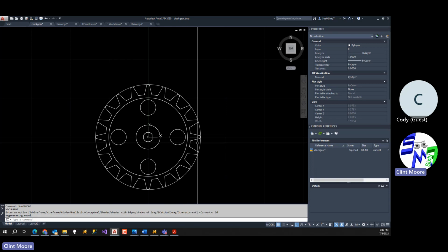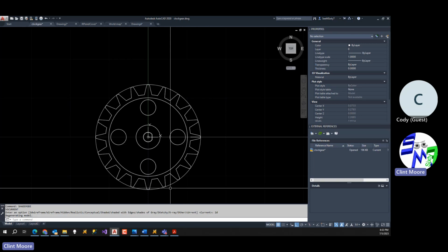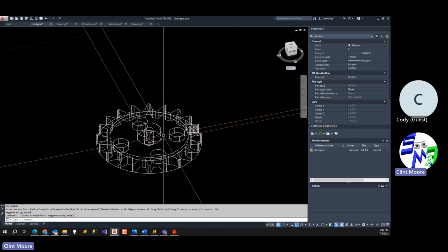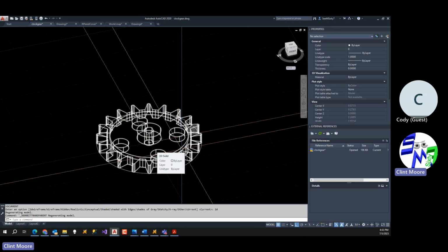the gear. Okay, and then from that point, we just basically extruded it, and then subtracted whatever we wanted to make the holes and make the cuts on it. And then from there, we took it to an STL file, and then sliced it in the Prusa slicer, and then dropped that on the little mini Prusa and printed it out. How's that, Brandon? Pretty cool.